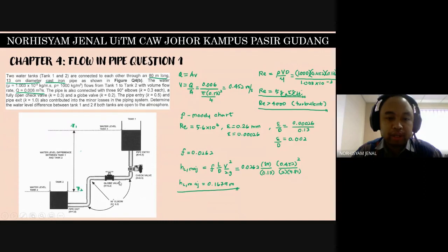And then we have, because the tank is open to atmosphere, the first thing that you need to know here is, P gauge at point 1 should equal to 0. And because this is the surface of a liquid in a tank, velocity at point 1 should also equal to 0. Here, P2 equals to 0 and velocity is also equals to 0.